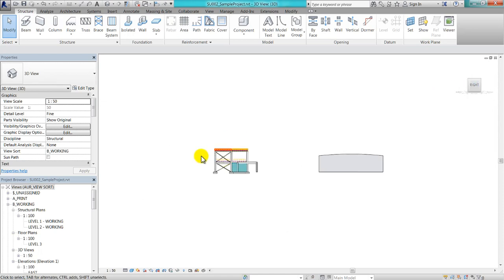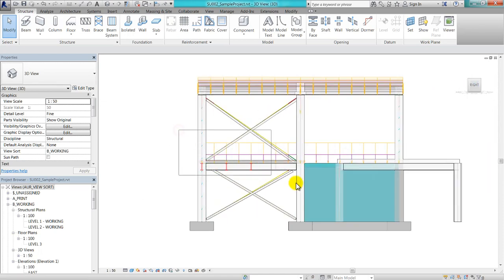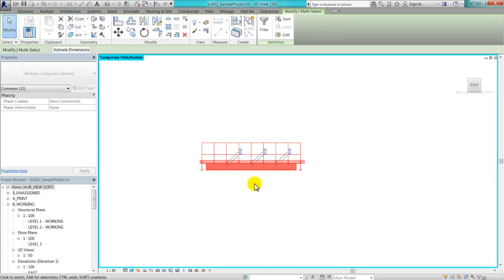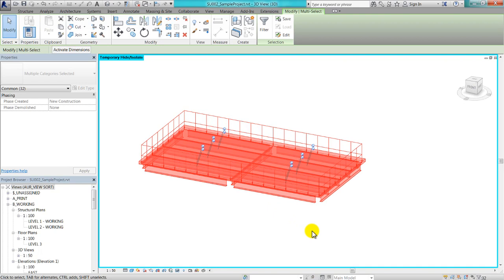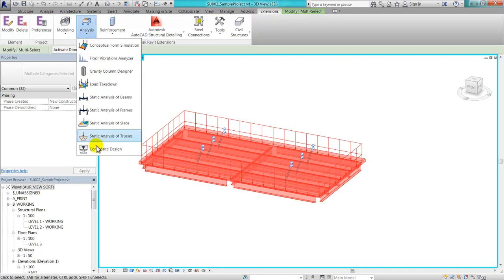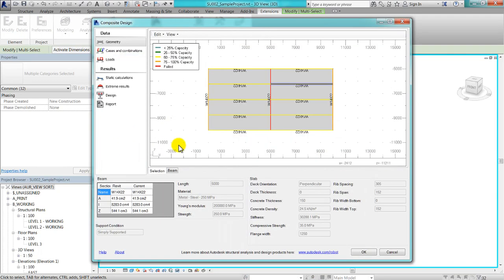Click on the right side of the view cube to select the composite slab, including all applied area loads and supporting beams comfortably. Hit HI on the keyboard to isolate the selection. While all elements are still selected, start the Composite Design tool from the Extensions ribbon. The Geometry dialog is displaying the geometric and material properties of the selected element.